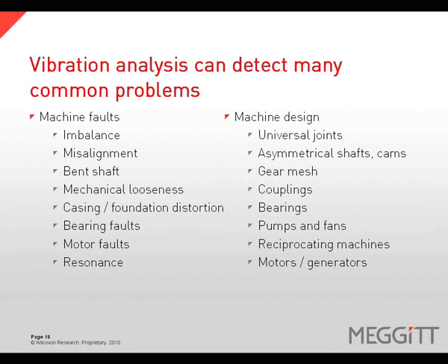Vibration analysis can be effectively used to monitor all sorts of machine problems. Because most problems have specific characteristics, by performing frequency analysis, we can differentiate between the various problems. Unbalance, misalignment, looseness, and bearing defects are just a few of the types of problems that can be detected.